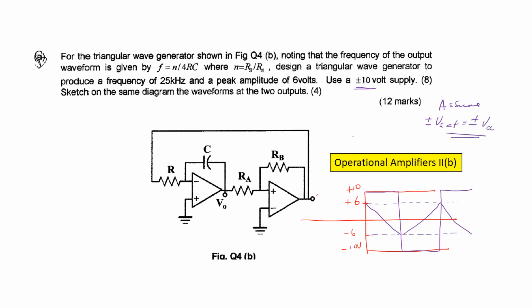If not, somebody can say, okay, it's a regular op-amp, so I am assuming that plus or minus VSAT is, let's say, 1 volt less than that, plus or minus 9 volts, and then you do the thing, perfectly all right for me, okay? But you have to say something. Don't just draw the thing and lose a couple of marks because you didn't tell me what the decision was. So always say what you're doing.